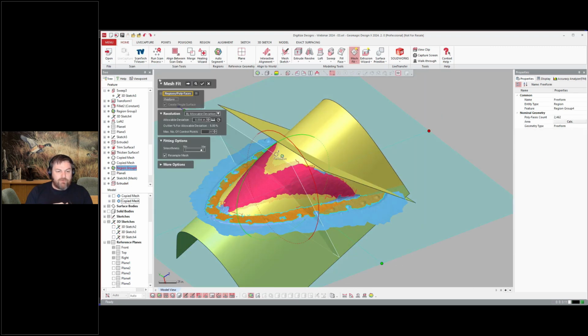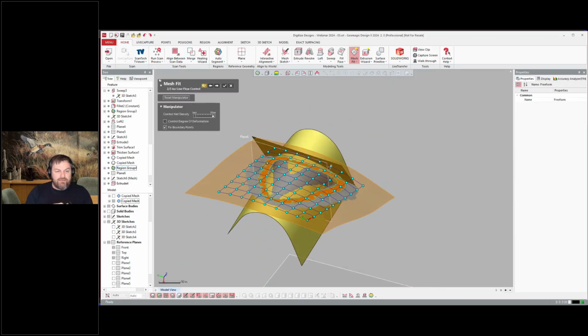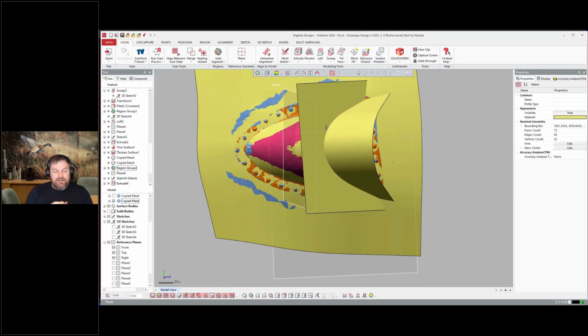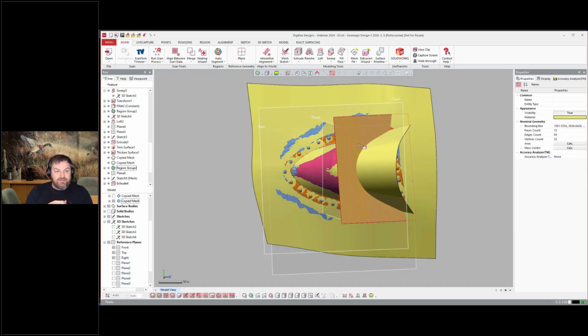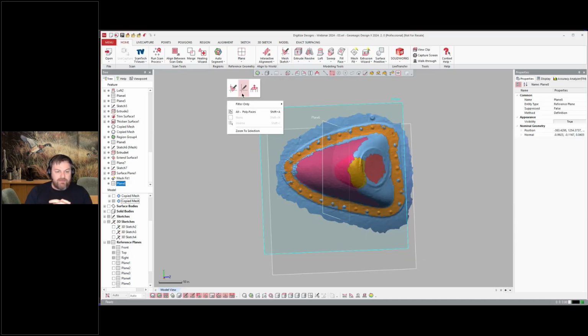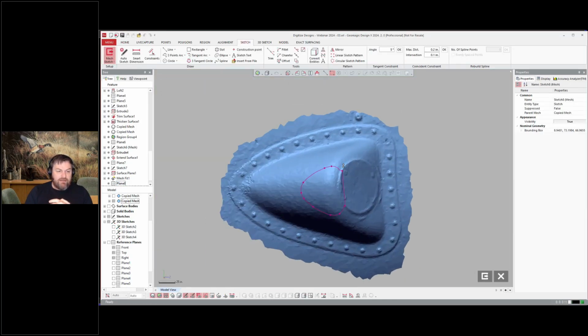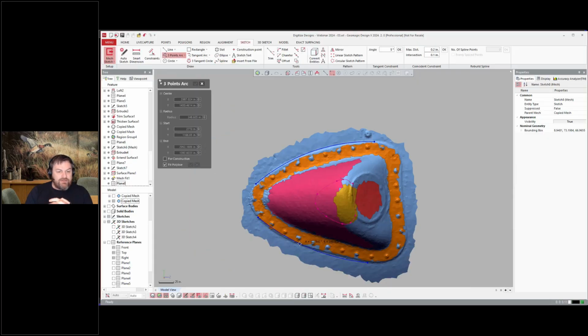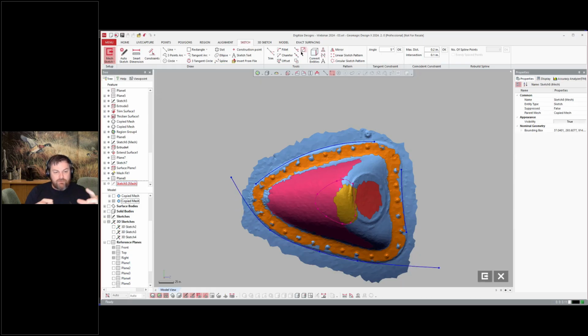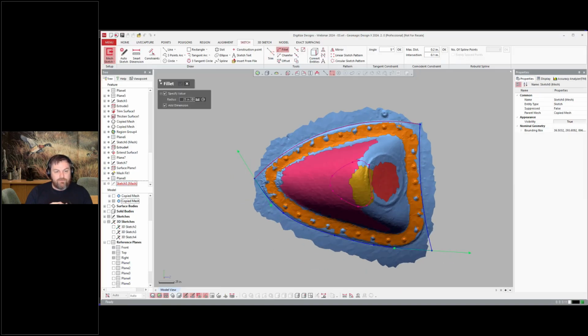So here, what we're doing is we're creating all the surfaces that would create this shape, right? And in that last instance, instead of doing a lofted surface, I went ahead and did a mesh fit. So I just used that one instead, just to show that there's another method to use, where I created this mesh fit to fit on that flange, the orange region. And then you'll see here that as you draw things, you'll see, is this an arc? Is this a curve? Should I use a spline for this? As you visually draw, you can identify what it should be and then apply the dimensions and constraints from there.